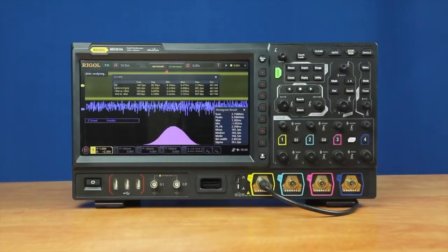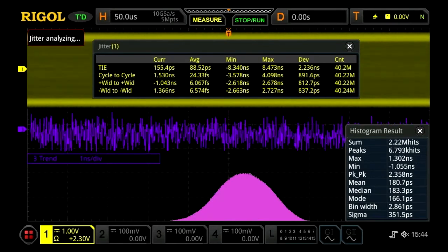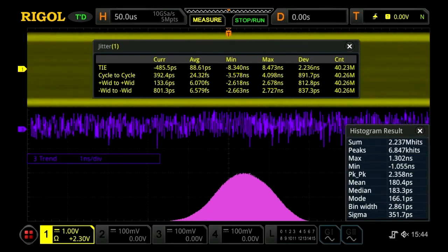These analysis tools enabled us to determine root cause and ultimately reduce the clock jitter. Zoomed in on our final result, the MSO8000 can characterize picosecond level changes in the clock period. This is well beyond what can be visualized with a standard oscilloscope without deep memory jitter analysis capabilities.